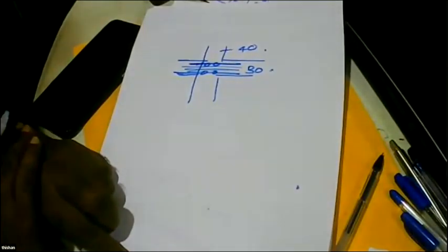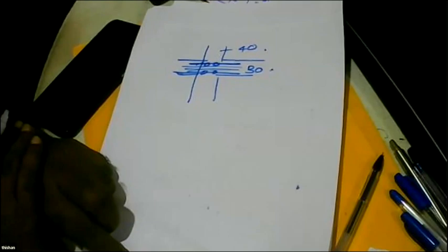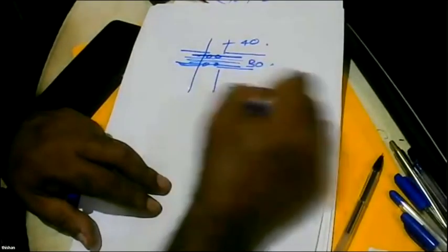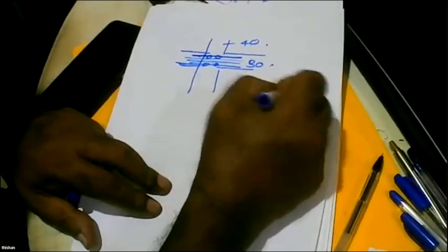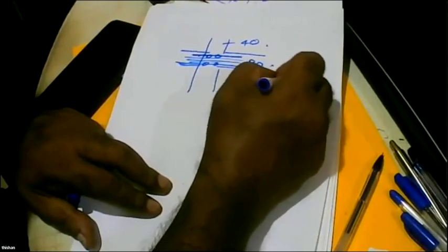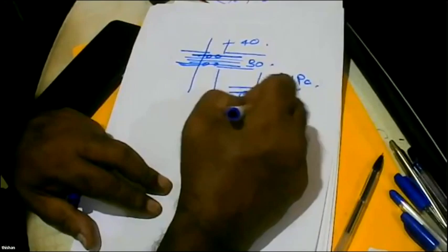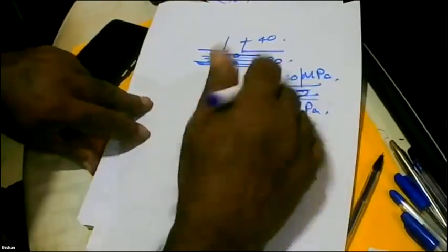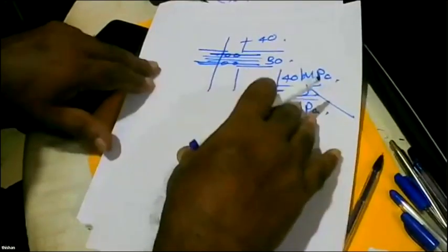So because of this huge amount of reinforcement, there's a huge amount of confinement. So even 30 megapascal concrete can easily transfer the load, that is the stress that is induced in a 40 megapascal concrete. So that's the reason. So even in a raft foundation, you have a lot of reinforcement in these directions. So you have 40 megapascal here. Here you have 30 megapascal. It doesn't matter because all these reinforcement can do the dispersion into the concrete.